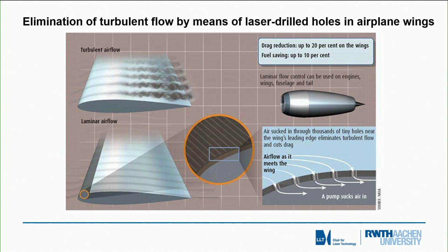from NASA, which shows you that depending on the position on an airfoil, we get turbulence, especially in the low pressure areas. And these turbulent flows mix with the bottom flows so that we get real big turbulence in the tail of a wing. Now this can be reduced, and it has been calculated that if we would be able to apply very many thin holes of an order of maybe 100 micrometer in diameter in that airfoil, then we could suck off these turbulent flows.